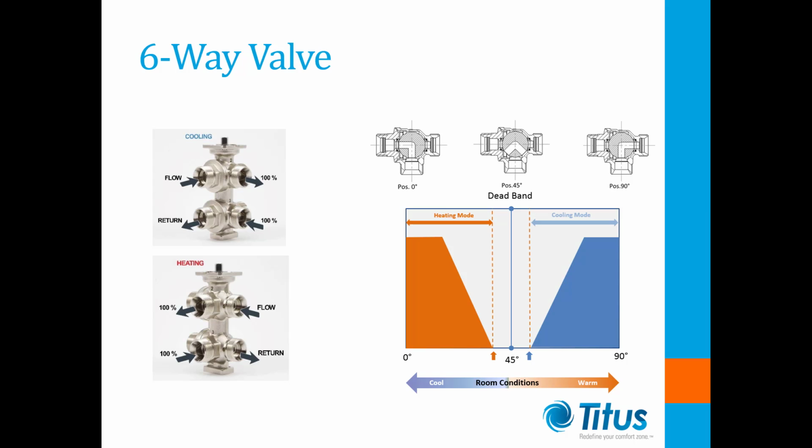An alternative design worth considering is using 6-way zone control valves. The 6-way valve was specifically developed for use with chill beams and radiant cooling systems to provide 4-pipe functionality into 2-pipe zones. The valve body consists of a set of hot and cold water connections with a common 2-pipe out to serve the zones. All 6 ports are operated by a single actuator, which reduces control costs compared to the other heating options shown so far.